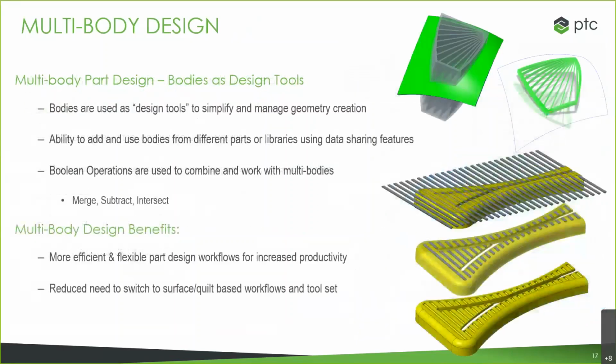This is something that's really powerful and really kind of a separate way to work here. So if you've never worked with multi-body design before, it's definitely something that you're going to want to try out. So for some people, the standard way that we're used to working in Creo is going to work just fine. It's still a great way to work with things like skeletons, published geometry, that sort of design methodology. But for many people, this type of Boolean work where you're merging and subtracting bodies is going to open up a new world of possibilities.